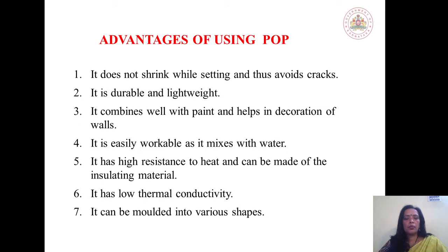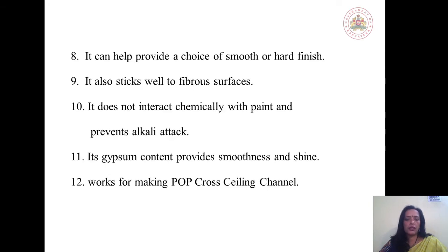The advantages of POP: it does not shrink when setting, thus avoids cracks. It is durable and light, and it combines well with paint and helps in the decoration of walls. It is easily workable as it mixes with water. It has high resistance to heat and can be made of insulating materials. It has a low thermal conductivity. It can be molded into various shapes and provides a choice of smooth and hard surface finish.